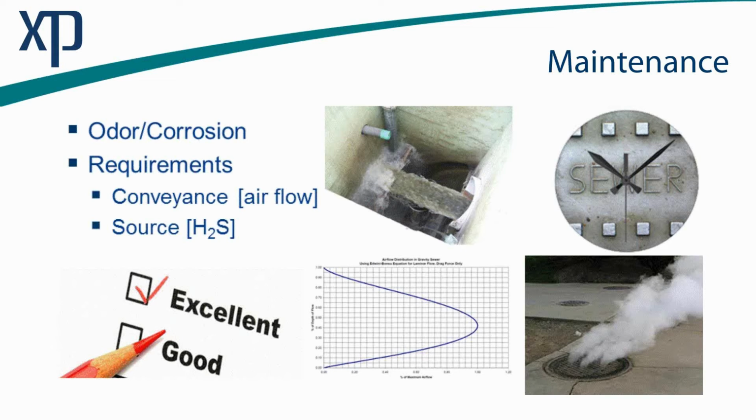Our olfactory systems are simply immune to hydrogen sulfide, and when we get to that point, unfortunately, it's lethal. So be very careful if you're inspecting these systems, opening lids. Make sure you vent them before you crack open a pump station and inspect these systems. We wouldn't want you to fall in, so be very, very careful with hydrogen sulfide.